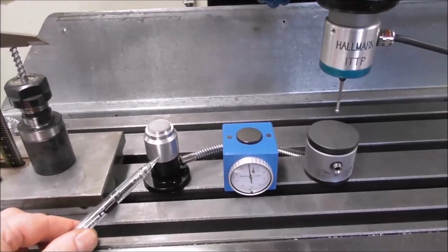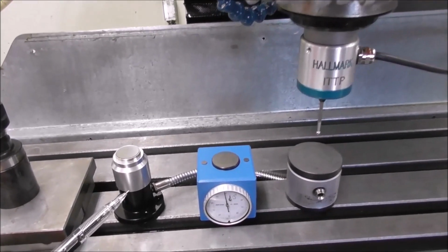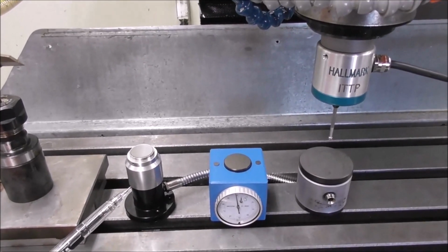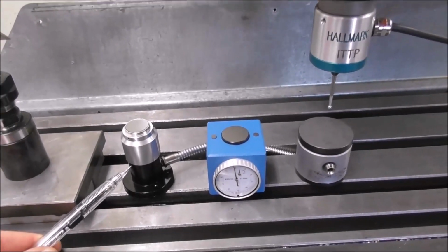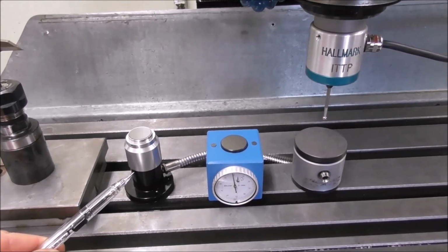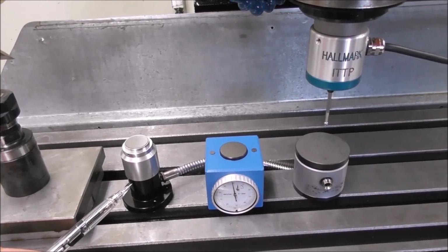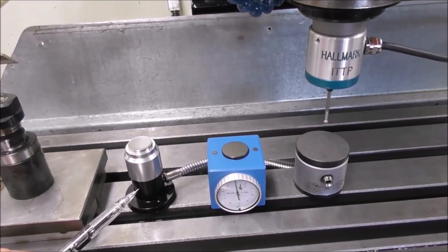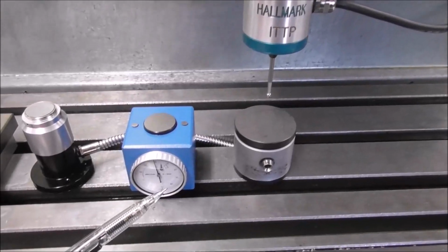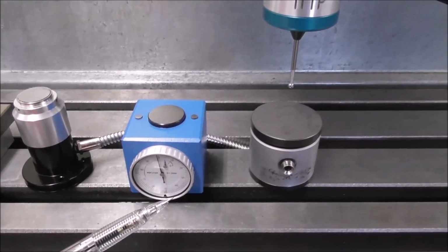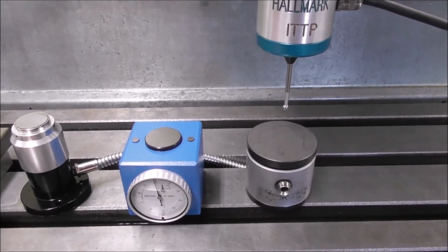So in order to justify the cost of an electronic tool setter and the added wiring and maintenance issues and risk to your machine, I would say you probably need to be doing quite advanced work so that you can capitalize on the added benefits of being able to do automatic tool length offset probing while it's running automatically from an automatic tool changer, testing for tool condition, whether there's been any breakage, tool wear, and so on. And I would hazard to guess that most people will not be using it for that application and would find it hard to justify over the cost of a simple mechanical tool setter, because you just have that very simple procedure of pushing one button to load the tool length into your tool table.